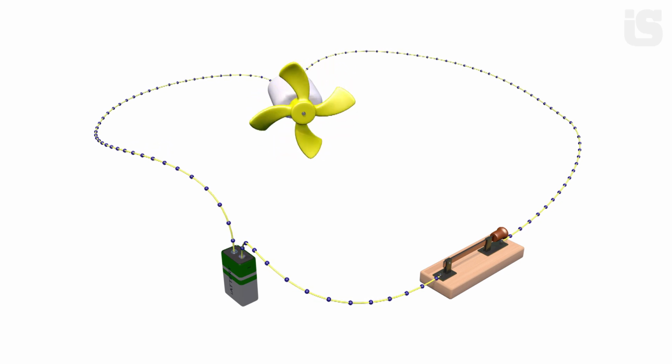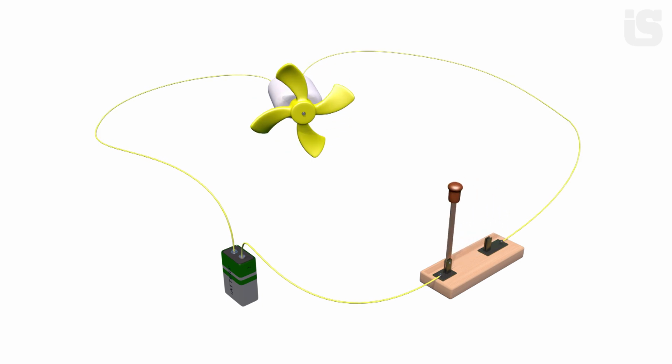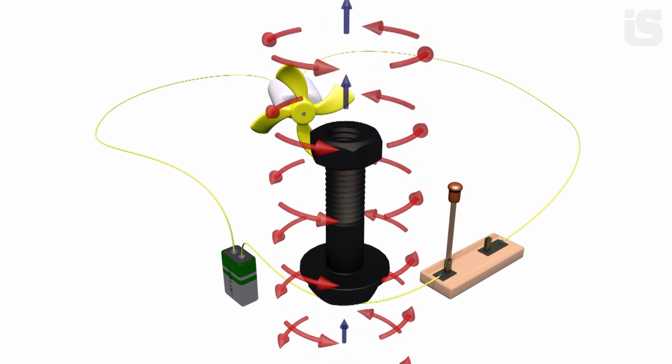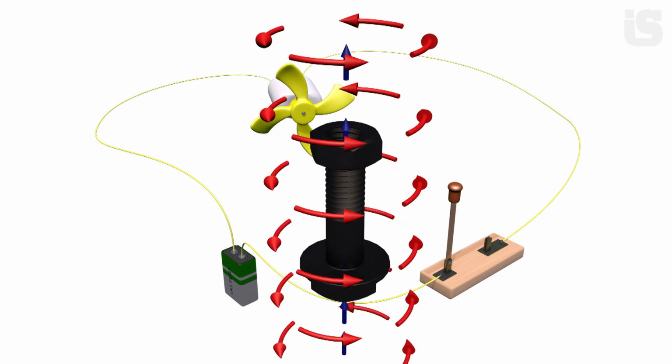Electric current also has magnetic properties, just like a simple magnet. And the direction of magnetic fields can be determined by the right-hand rule. If you take an electric wire in your right hand, wrap your four fingers around it, and straighten your thumb, the thumb will point in the direction of the current, and your other four fingers will point in the direction of rotation of the magnetic field. This can be explained more simply.